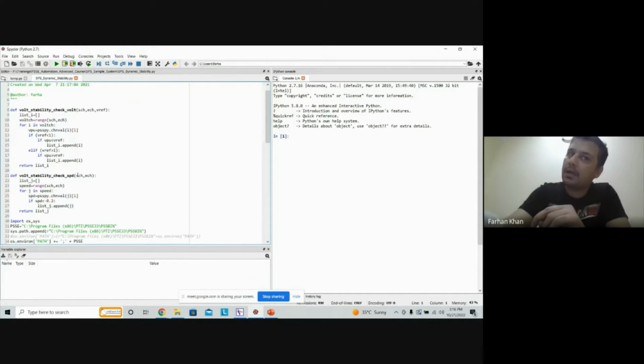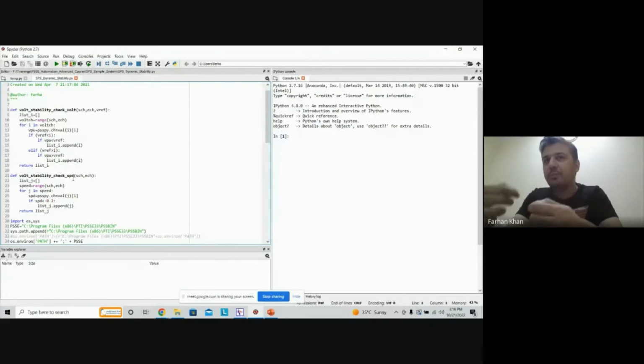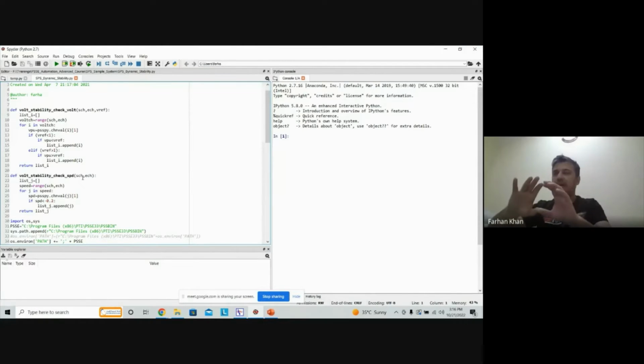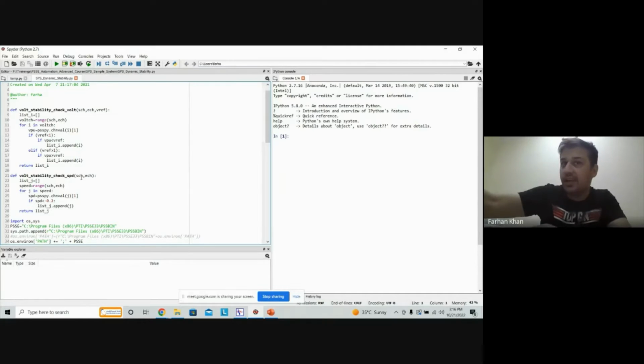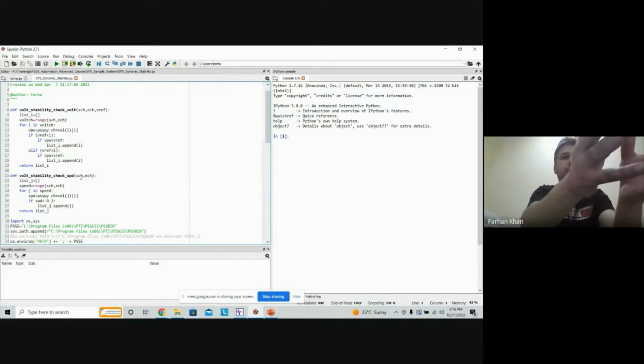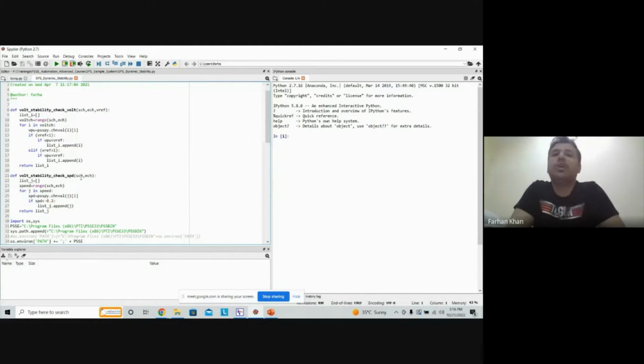Similarly, for checking the speed of different motors which I have modeled within my system, I'm using here SCH, the starting channel, and ECH, the ending channel. If I want to check my entire simulation, the monitoring of multiple channels within my system, that is why I'm doing this. Instead of checking each particular channel, I'm checking a bulk of channels at a time. All those channels which violate my particular threshold are going to be reported to me. So this is how this code is written.